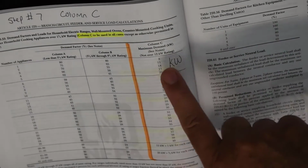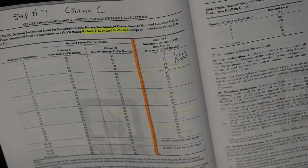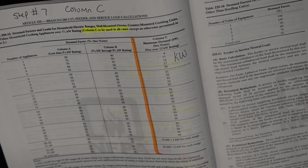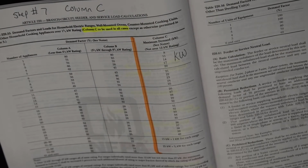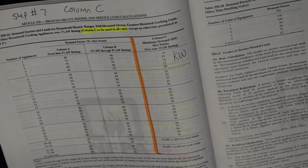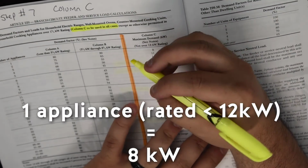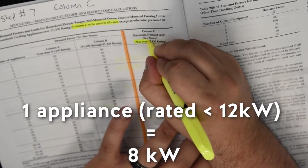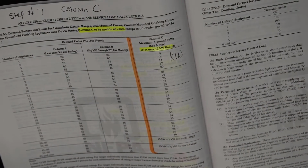What I mean by that is it says C notes because column C is only for not over 12 kW. What if we've got something more than 12 kW, one range or a group of cooking units that's over 12 kW? So the way that column C works is if we've got one appliance and that's 12 kW or less, we're going to put in our calculation 8 kW. If we've got more than 12 kW, we're going to have to see the notes.